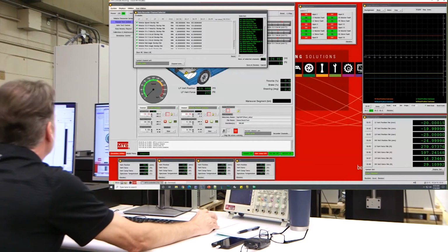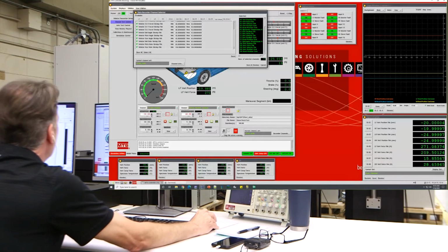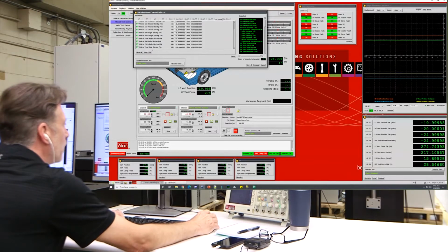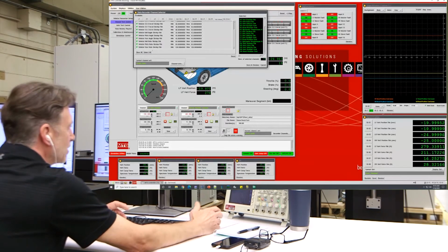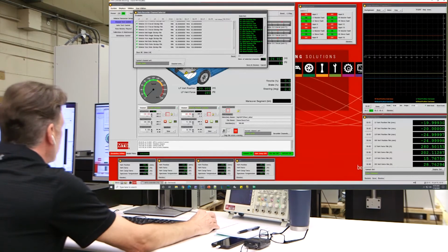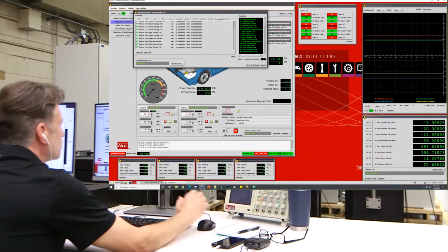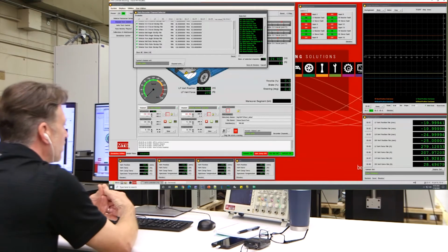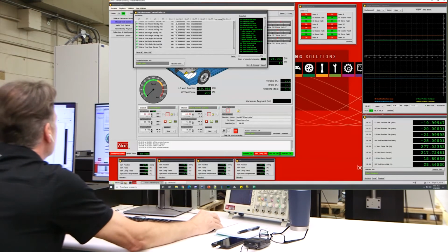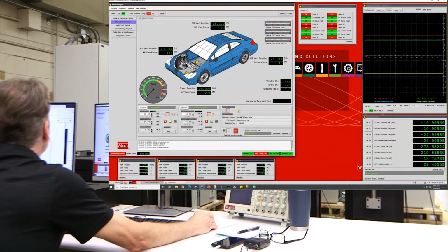At the CG, we've got velocities, we've got accelerations, we've also got your typical roll, pitch, yaw angles, as well as rates. So any of the metrics that you typically collect for your ISO handling maneuvers or whatever events that you record on the track, we've got the ability to record this all together in one synchronized data file. With that, I'm going to just close this off and return back.